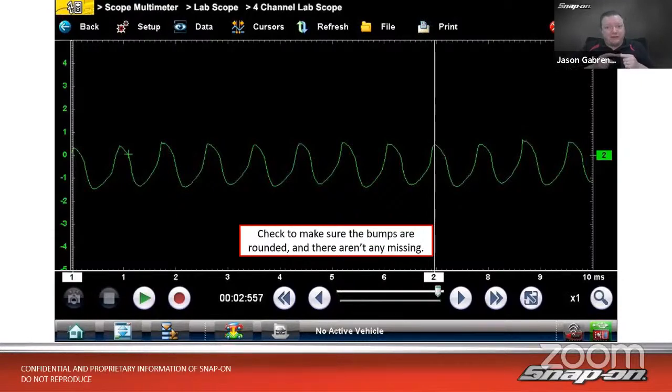Now, those are the kind of no starts you fix with tapping the bottom of the gas tank, right? You tap the bottom of the gas tank, it vibrates the fuel pump, and then it vibrates to a good commutator, and then amperage can flow, and then it'll turn. And then it stops on a good one, and then it starts, and that stops on a good one, and that starts, and it stops on a bad one again, and now I have a no start again. So those are the ones that get fixed if you pull it off the back of the flatbed or something like that, or you tap the bottom of the gas tank, and it fires right up.